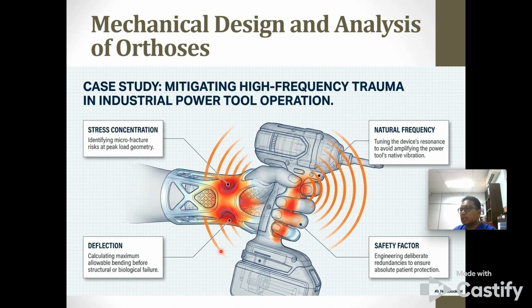Okay, this is related to your assignment or report later on, where you measure the vibration from your tools and also measure the vibration transferred to your hand. From that you can refer to the chart and make some decision: does this device have high vibration, and is it okay to use for a certain length of time?